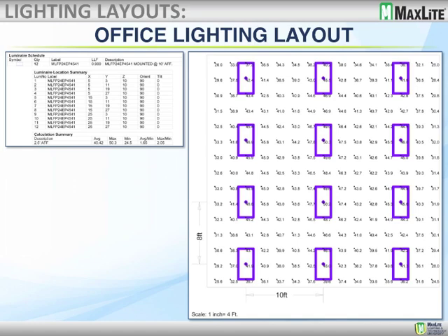It was just a 10-foot height and a 30 by 30 room, and we went to see how many foot candles we ended up achieving. So with this, at 2.5 feet above finished floor, we were able to achieve 40 foot candles. This was within the range that the customer was asking for. So David, once you're giving the customer what he wants here, is he able to understand this type of information typically, or do you generally have to explain what they're looking at?